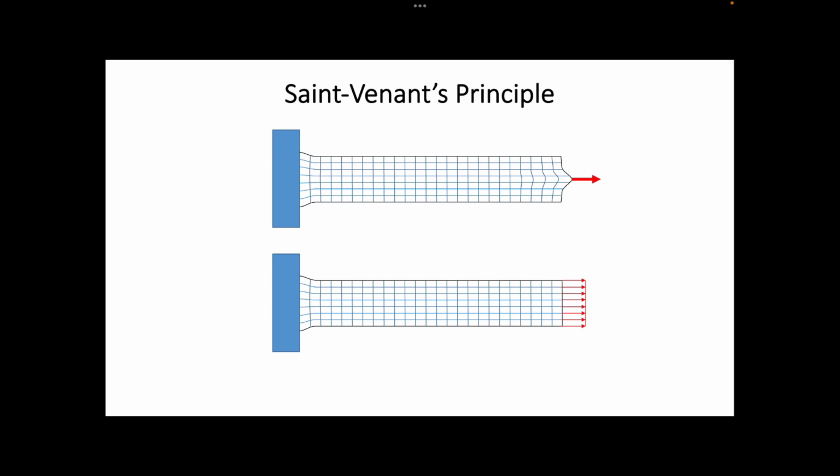So if the materials remain elastic, based on the stress-strain relationship that we learned in the last lectures, we can predict the distribution of the normal stress at the location of each vertical line. To visualize such distribution, let us section through each bar at two locations, and then plot the stress distribution on each cross-section of each bar. Since the vertical lines are distorted for the top bar, there is a clear difference in the stress distribution of the two bars in this region.